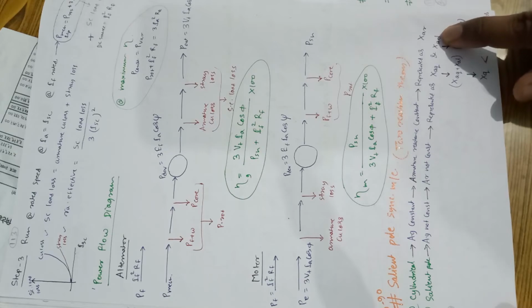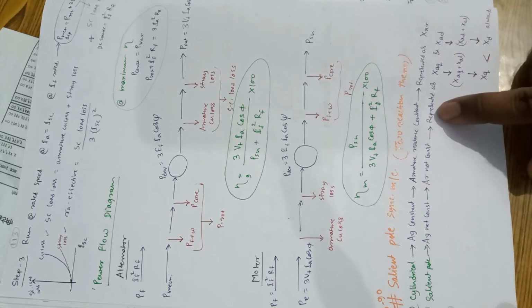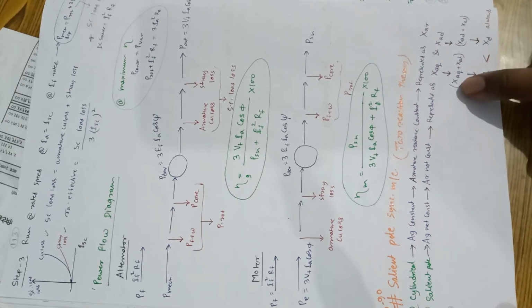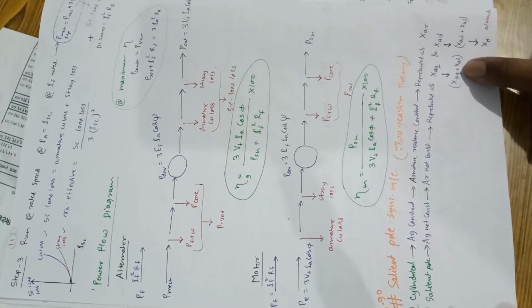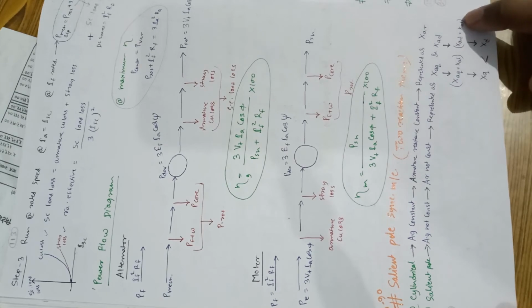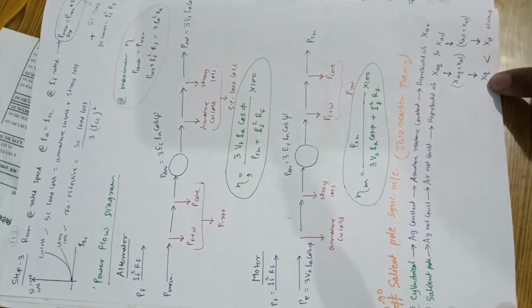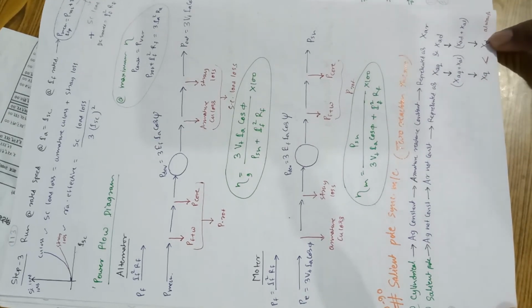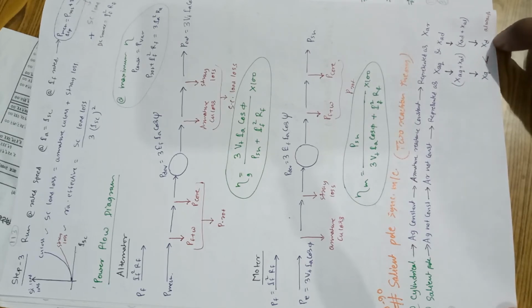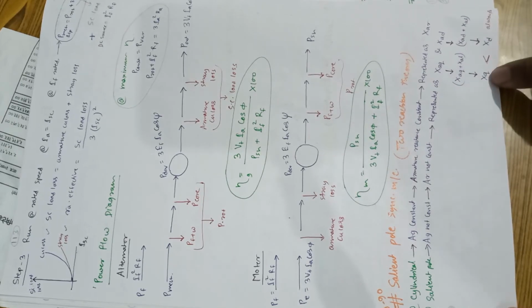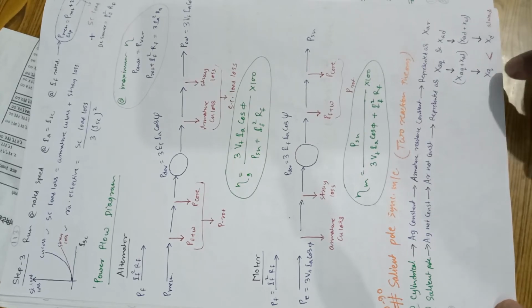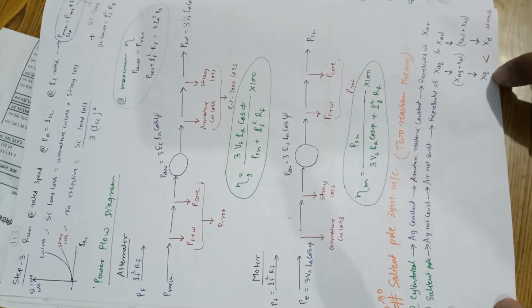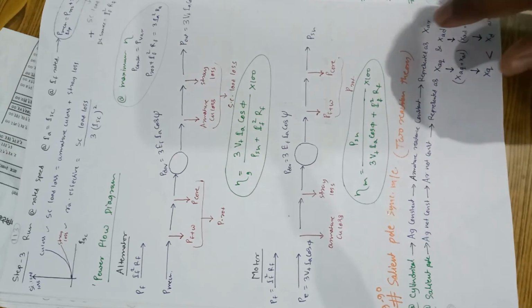Okay, xaq and xad, and when we add the leakage reactance xal, it becomes xaq plus xl and xad plus xl. So finally we write it as xq and xd, and remember one thing, that xd is always greater than xq. Okay, xd is the direct axis synchronous reactance and xq is the quadrature axis synchronous reactance. Okay, when we talk about the formulas,